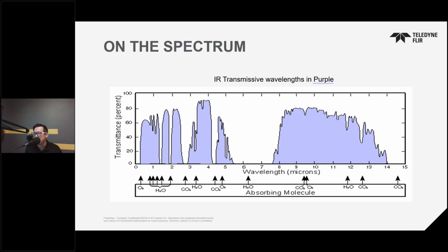And so how do we deal with it? Well, if you remember from the cooled detector diagram, we applied a cold filter that cuts off sharply at around 5 micron for mid-wave detectors, and at around 7.5 micron to start the long wave band. So that's how we get around it. This is really the most basic and most common example of applying a filter to manipulate the spectral response of a camera, with the endpoint here not being to exploit some specific material or target in the scene, but to avoid noise from the water band in the 5 to 7 micron range.